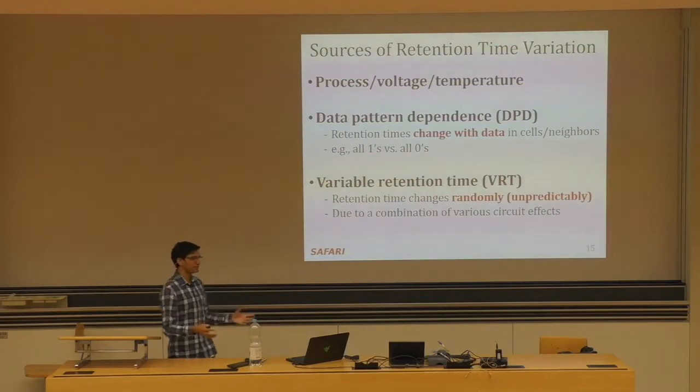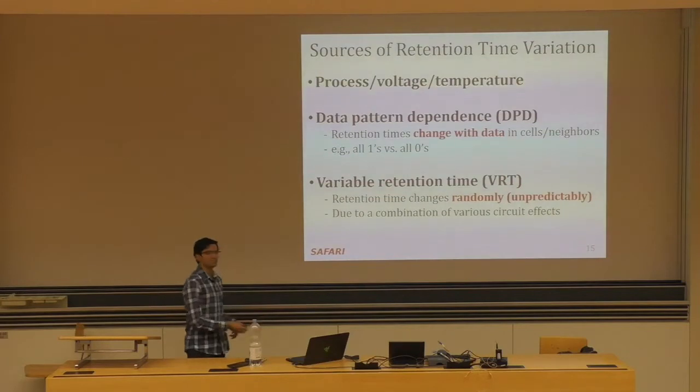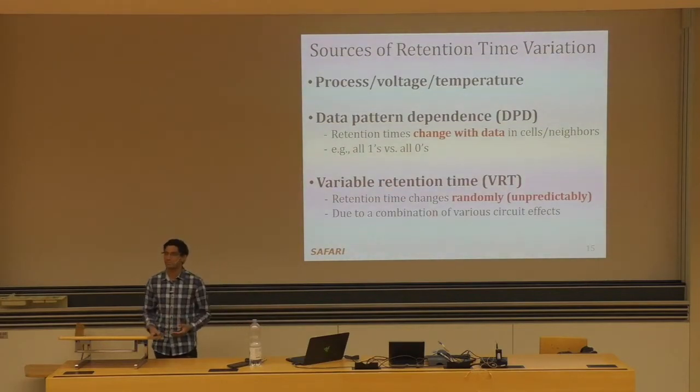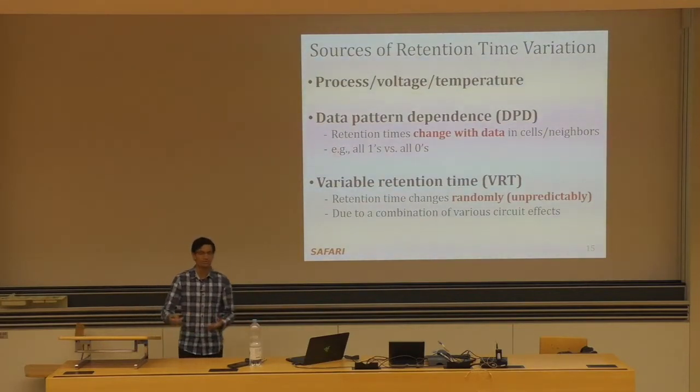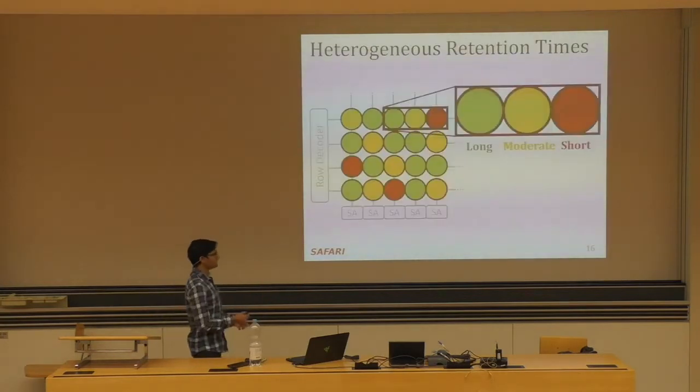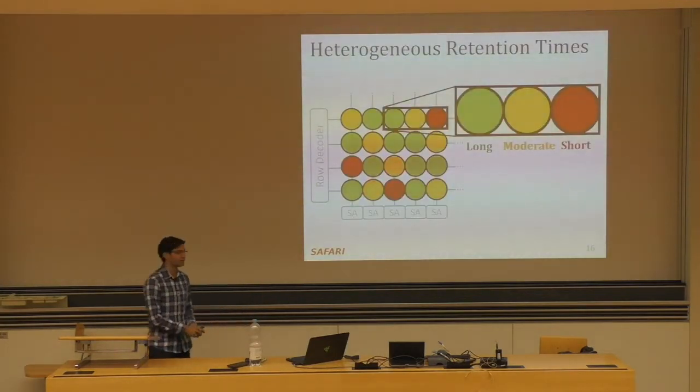And this occurs due to several various circuit level leakage phenomena. But the problem for us is that this is unpredictable, and so these cells will be changing retention times all throughout DRAM operation. So now let's take a look at a more realistic picture of a refresh operation.